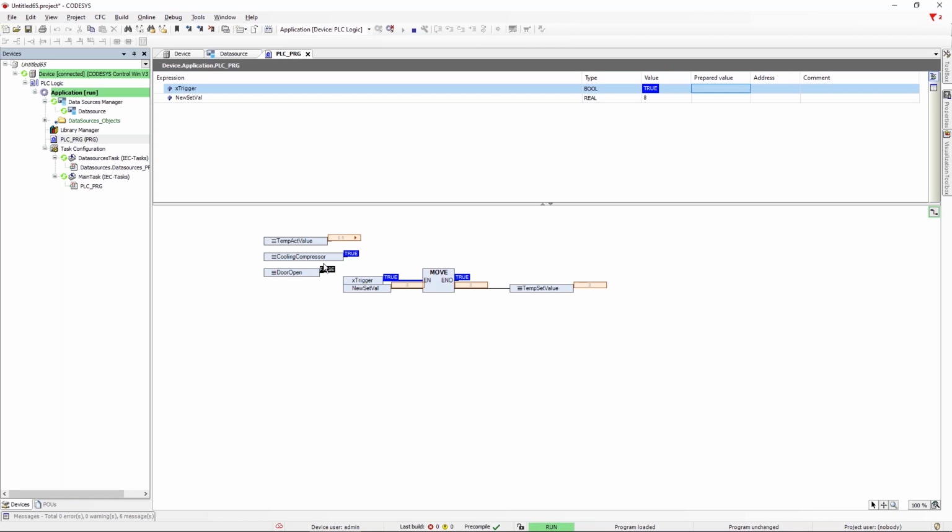They were just imported from OPC UA, from the server, and in this way I can easily have a communication between server and client. And of course, I could in the same project have as well a server configuration and therefore have a bidirectional communication between server and client.